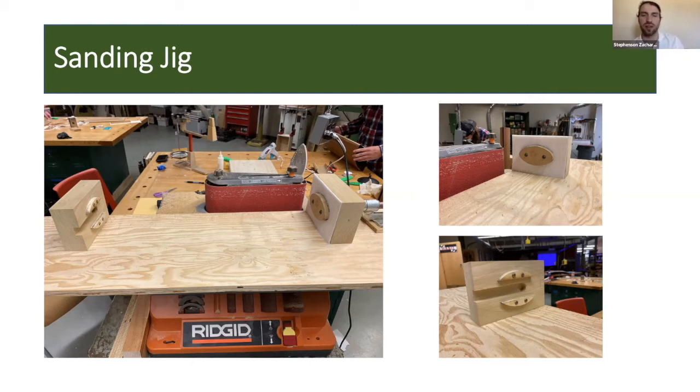In order to hold the lamp tightly without crushing it, we had to add this piece of white felt to the sliding block to widen the tolerances a bit and give it that nice cushion, so that you're right in between holding it tightly, crushing it, and holding it too loosely.